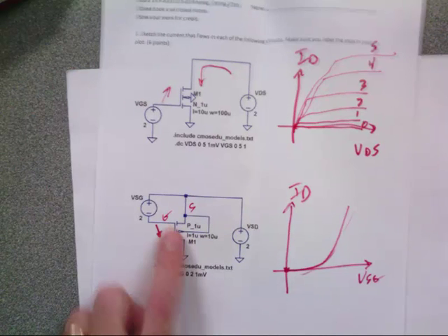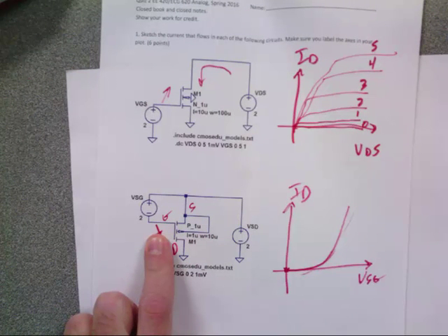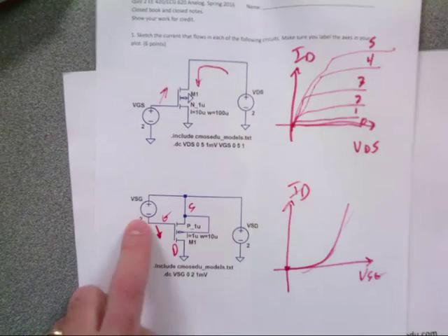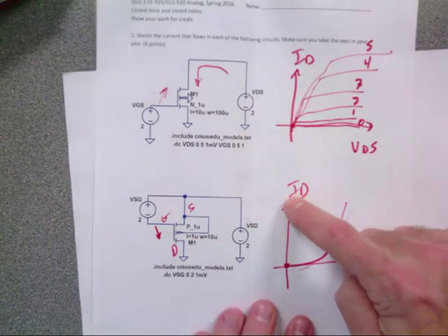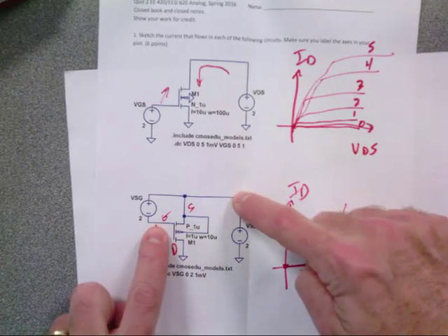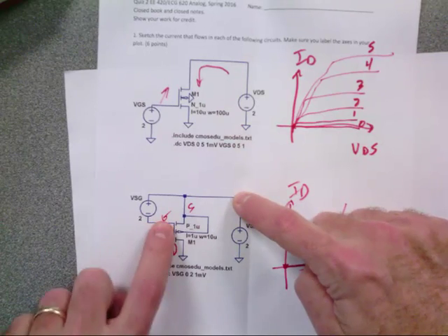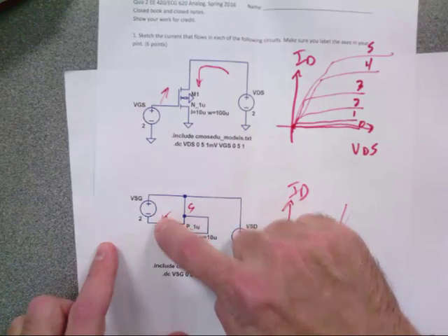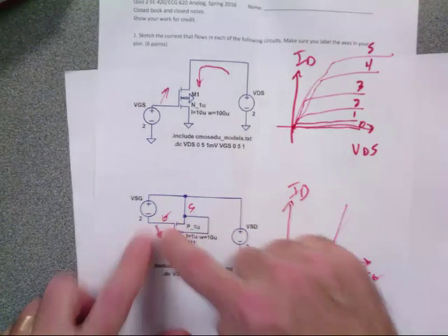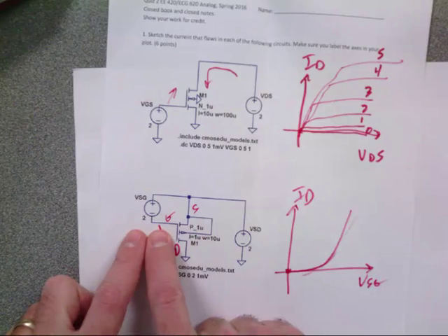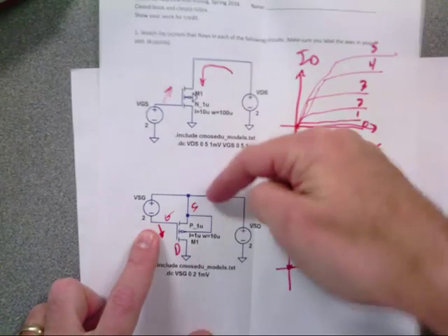Would be a diode as, I don't know. I would need to think about it, because this is VGS. So I'd take this voltage and subtract. Without thinking too deep, when this was 0, this is 2 volts, and if that was the gate to source, then it would be like a diode connected and I'd be pulling the gate up. Now, as I drop this voltage down, I would shut this off until it got to 0, because when this is 2, this voltage is 0. Oh wait, let me ask that. What's the voltage here?